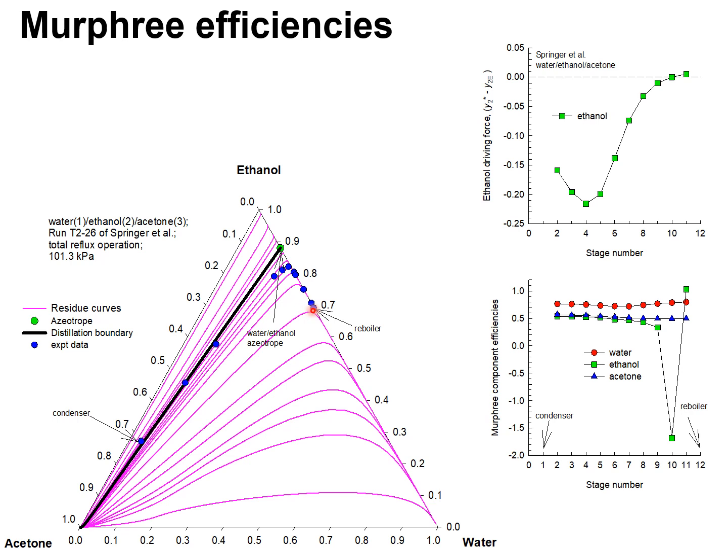The experimentally determined composition trajectories are shown by these blue circles, and the first thing to note is that this is the reboiler composition and this is the condenser composition, but the condenser composition is on the left of the distillation boundary. So the boundary has been crossed in these set of experiments.